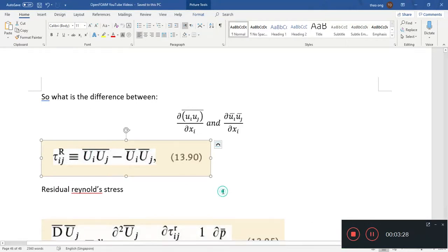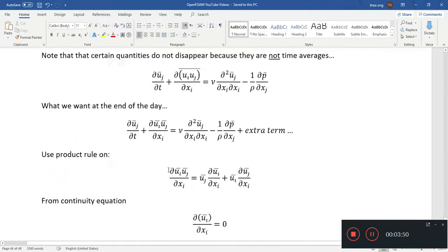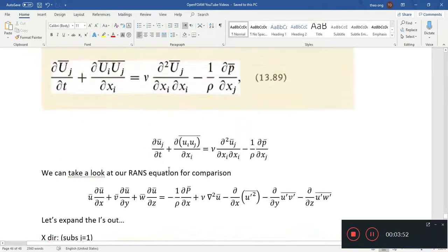These are stresses due to the small turbulence that we have to model, and we don't resolve directly through the simulation, but we model, in a similar concept to k-epsilon, but not exactly the same. We just model these small subgrid scales, meaning smaller than this delta that you specified.